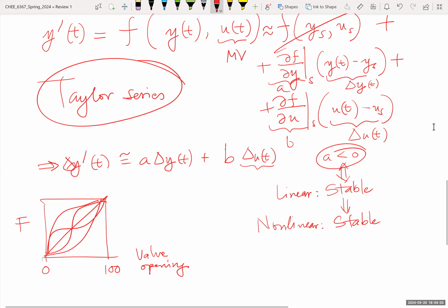And then what you do is you take that function, put the inverse of that function here in delta U, so that you can have essentially a linear effect from whatever it is you assume to be manipulated to the output. Right? So that's a trivial part of removing a nonlinearity. The dynamic part, which is more interesting, is typically handled like this. That's what people routinely use, overwhelmingly, almost always, assuming a linear system.